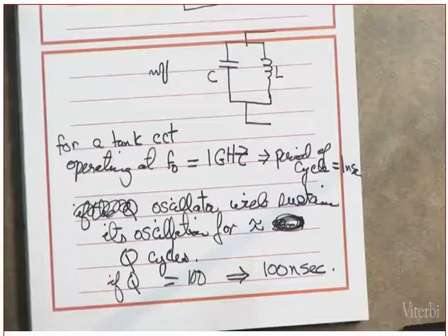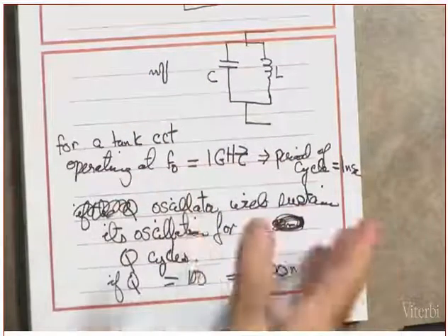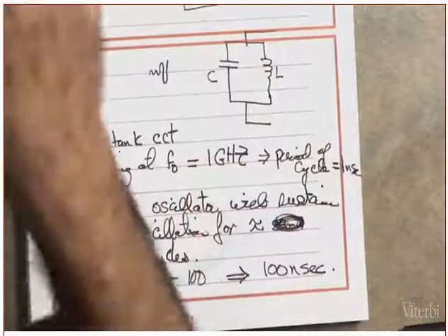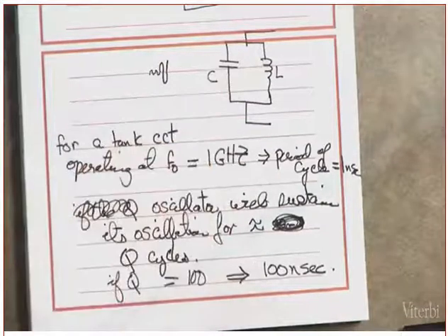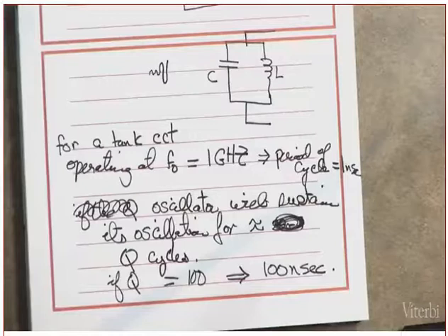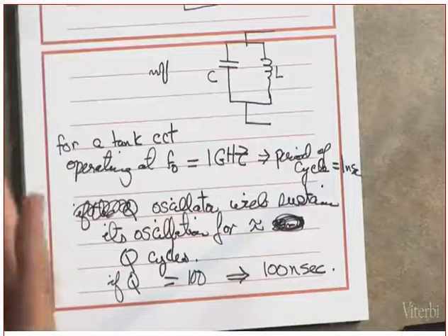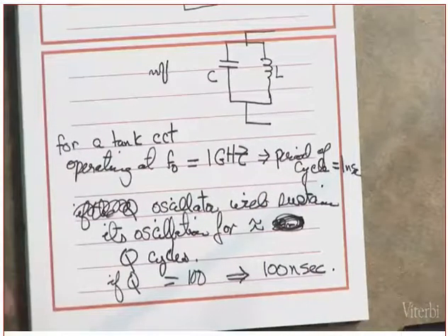Do we need an amplifier? What do we need the amplifier for? We need the amplifier to sustain that oscillation, to put energy back, to recover from the energy lost in the resistance. Did you understand that or not? The resistor loses energy, dissipates power. We need to replace that. How do I replace that? I replace that only by using an amplifier. Clear? Yes or no?